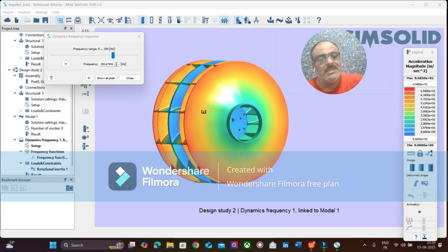Similarly, here there are going to be some shock loads or additional loads generated, because we have given a pulse to check what kind of g force it is experiencing. We also need to find out whether the impeller is going to sustain that g force. In this case it is almost about 6.5 to 7 g. The impeller is supposed to sustain that 7 g. If the impeller is not able to sustain this load, then there should be an optimization or a design change.